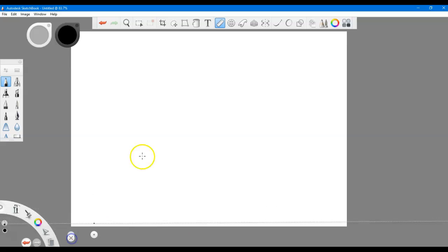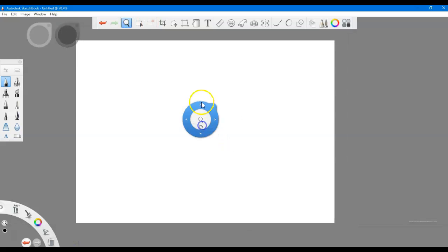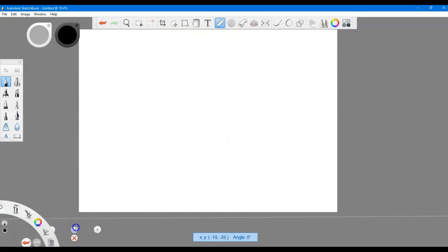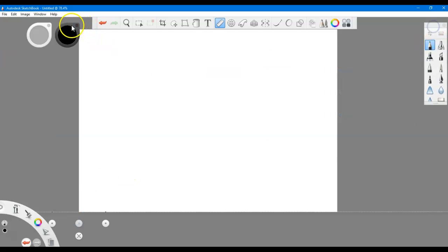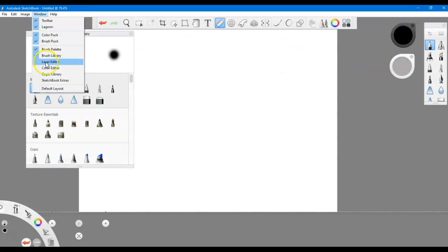Now this can be a little bit fiddly. All right, so you might have to move your page around like I have had to, and so on, until eventually you get to 0, 0, and your angle is set at 0, not negative 0. Because it's an A4 sheet of paper, our borders are 10 millimeters by 5 millimeters by 5 millimeters, and so on.